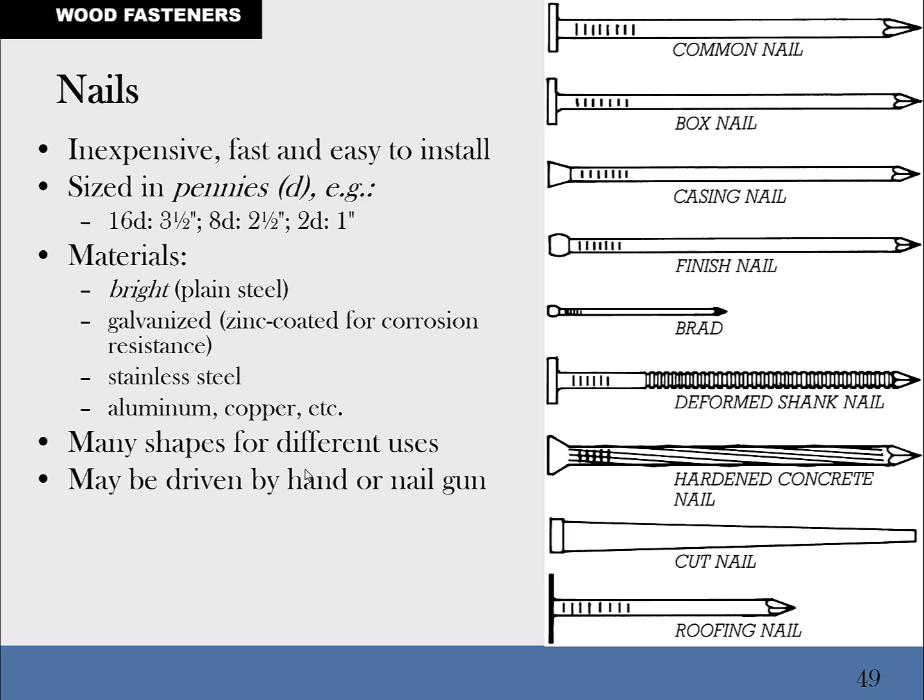They also sell a coated sinker, and the coated sinker has a sticky substance on it that will stick to the wood. As you drive it in, it's fine, and then when it comes to pulling it out, it's kind of gotten stuck there. So with the ring shank or the coated sinker, you tend to pull off the head and you don't get the rest of the nail.